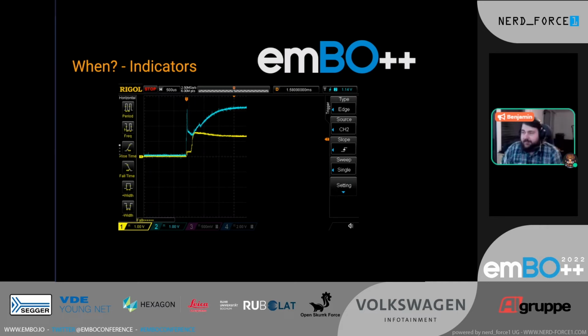And as you can see, there's a spike in the current, in the voltage. This is the initial spike because nothing is powered on. And then you can see a slight drop off from this area down to this, where it starts to stabilize. And this is essentially different components of the chip coming online and increasing the power draw.